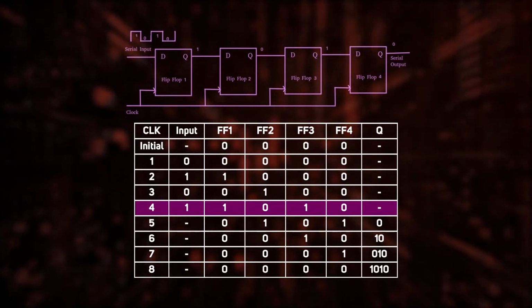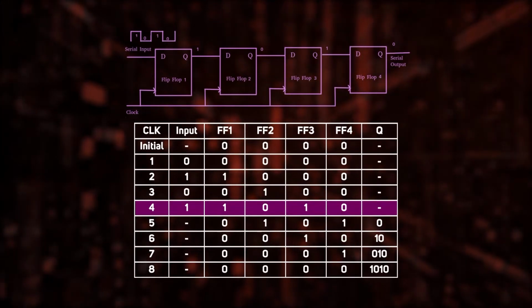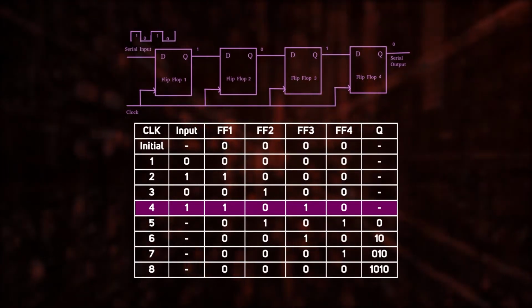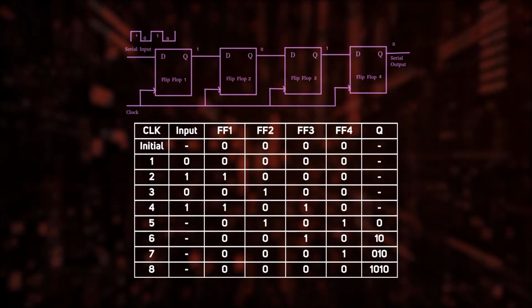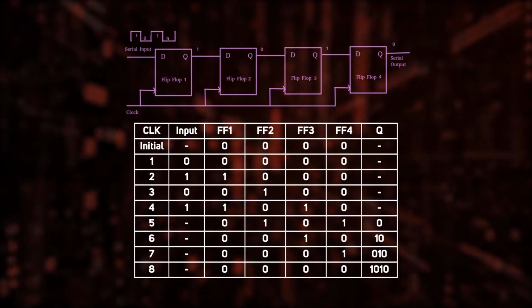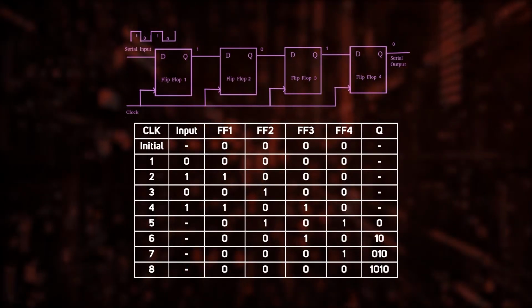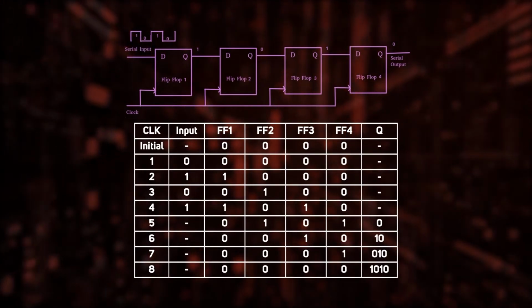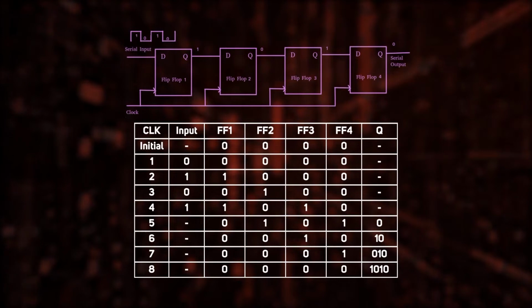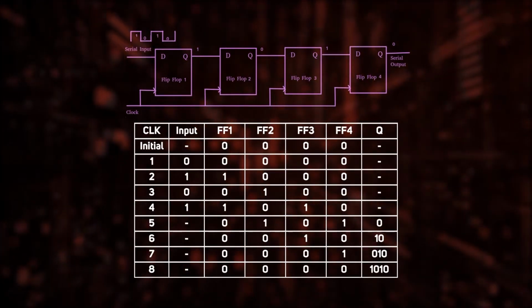So, it took around 4 clock pulses to store the value inside the register, and if we have to shift this value to another shift register, how many clock pulses may we require? Yes, another 4 clock pulses to shift these 4 bits to another shift register. Here also it must perform identical operations to shift the value as we have seen while loading the data to the register. Look at the table.